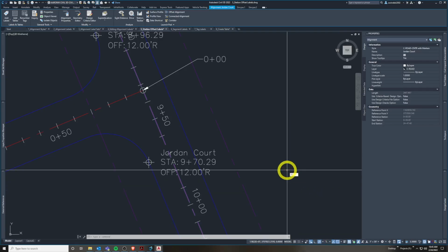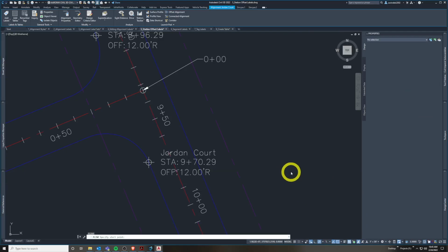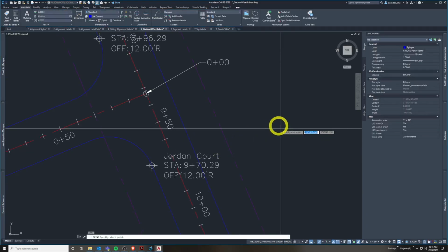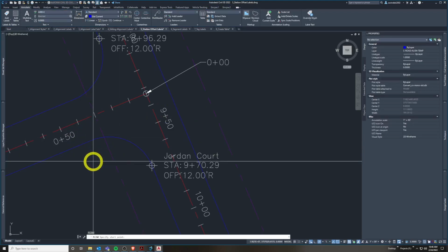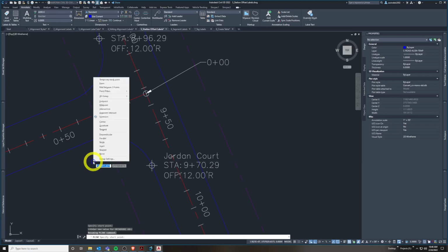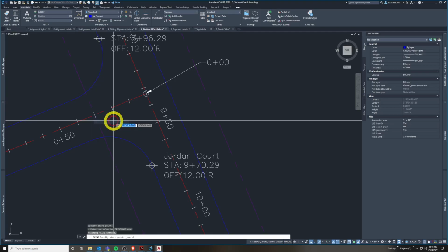They'll stay running until you turn them off. If you draw a polyline, for example, and you only want to snap to circles just for one command, this is when you would hold shift, and while you're holding shift, right click and say, I only want to do center just for this one command. It's a little bit of a deep AutoCAD command, but it's really, really helpful. Center.